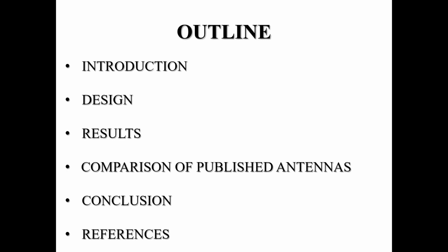Antenna plays a crucial role in aerospace communication by transmitting and receiving radio signals between aircraft, satellites and radio stations. A wide range of antennas including semicircular, L-shaped, triangular, multi-slot and U-shaped antennas are used in aerospace communications. Techniques like changing the ground plane with parasitic elements, adding a small fractional component, U-shaped or circular slots and circles are discussed to enhance their performance.